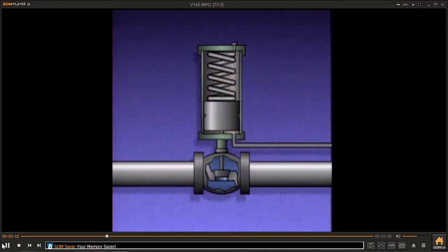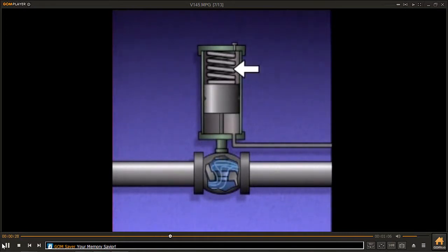It's called a single-acting piston actuator because a controller or similar device controls the air pressure on one side of a piston. When air is fed through this air supply port, the piston moves along in a cylinder, compressing a spring and opening the valve. Air on the other side of the piston leaves the cylinder through an air vent.